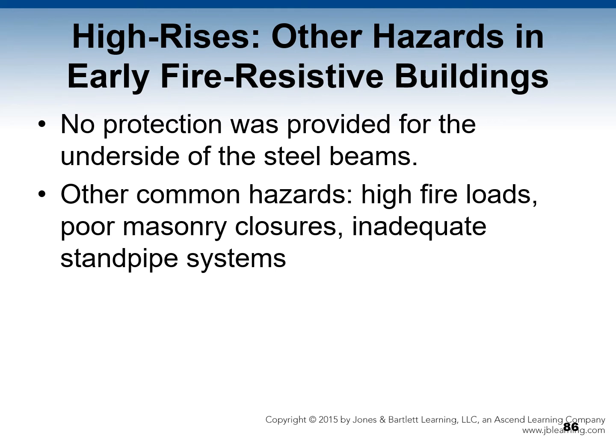Standpipes in older buildings may be inadequate in size. Closures are not often as fire resistive as the original masonry walls. Live loads in older buildings may have increased beyond acceptable safety limits. Unprotected steel supports may have been inserted. Fire loads may have grown to high levels.